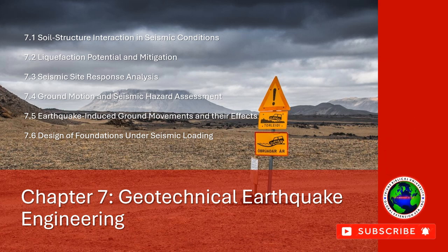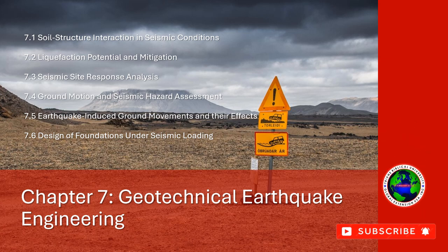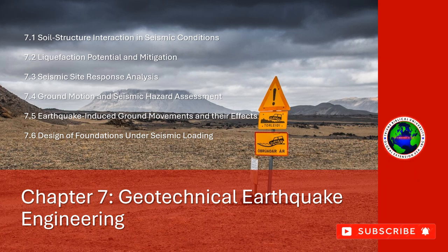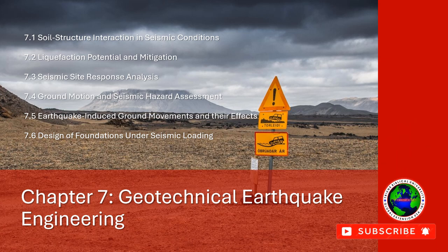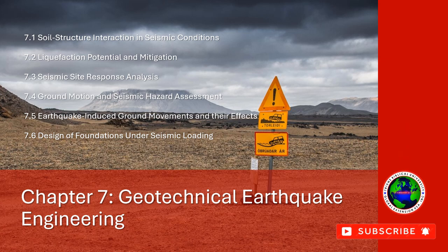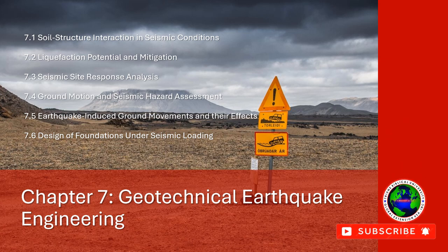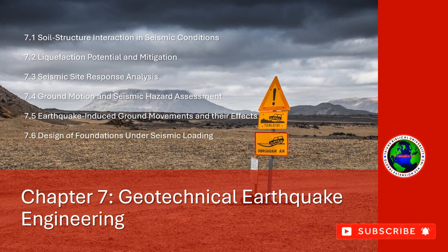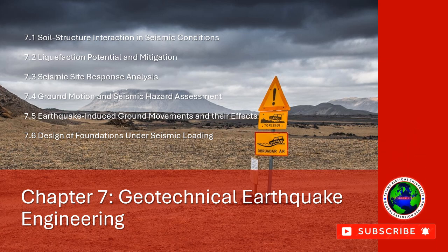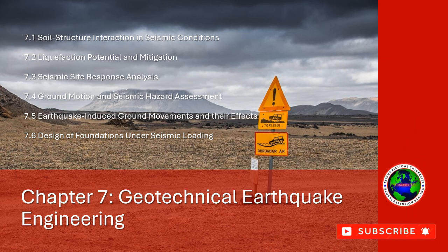4. Nonlinear soil behavior. Soil behavior during seismic shaking is often nonlinear, especially for soft, loose, or saturated soils. As the shaking intensity increases, soils may experience plastic deformation, which can reduce their stiffness and modify the seismic response. This requires nonlinear models in the analysis to accurately predict soil behavior under dynamic loading.